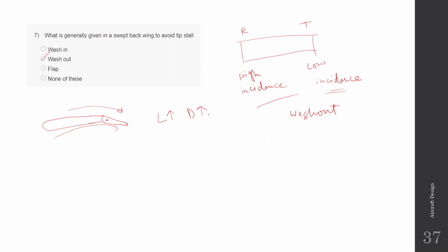So in this case, the lift is more, the drag is also more. These are usually used only for takeoff and landing. These high lift devices increase CL max by a good amount, so CL max is increased by a large amount and the V stall reduces significantly. But since the drag is higher, you need more thrust to maintain equilibrium. So these are only used for takeoff and landing, and usually for takeoff and landing, more thrust is also required.